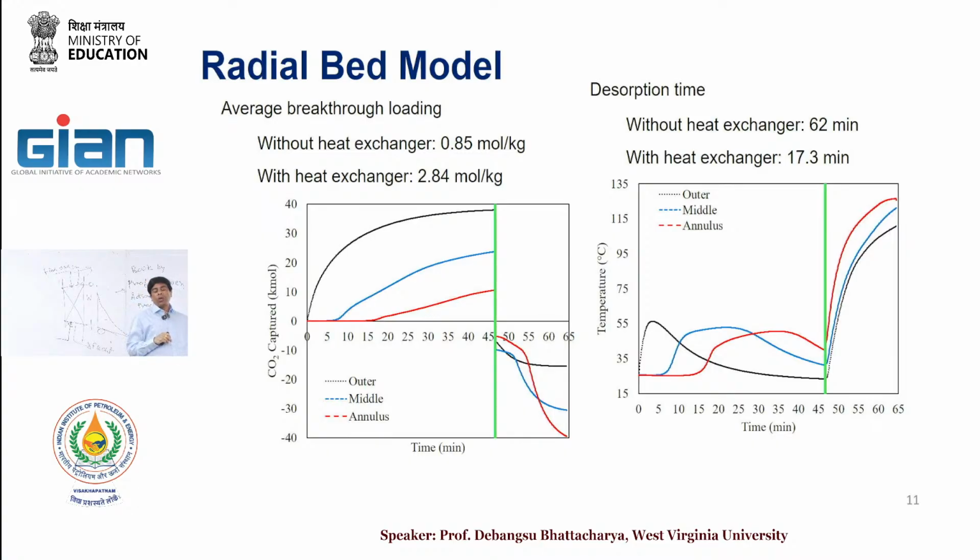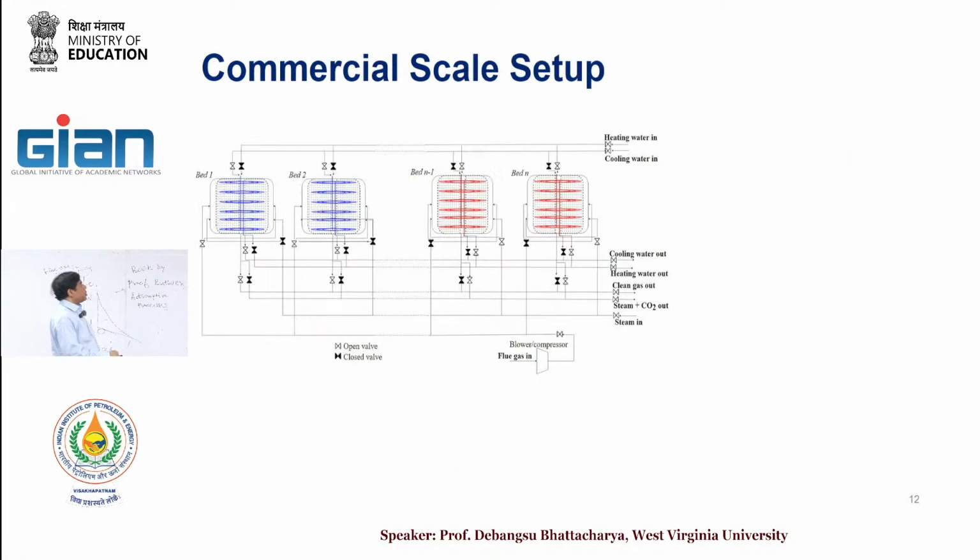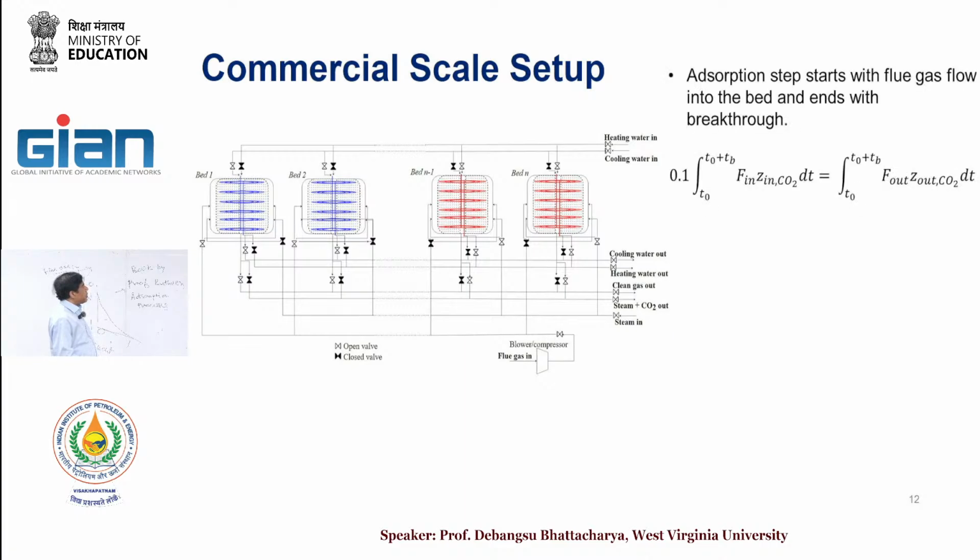So for all of these cases, when you actually do it yourself, you have to do two things that I discussed before. Equation scaling, variable scaling is absolutely critical. Without that, you will not be able to converge this. You have to also go through each equation one at a time and say, is it well conditioned, is it well posed, under what conditions can it actually degenerate, and all of that. So this is definitely a challenging problem, but it can be done. AspenTech, the solvers, have got all of these things, but you have to kind of help it.